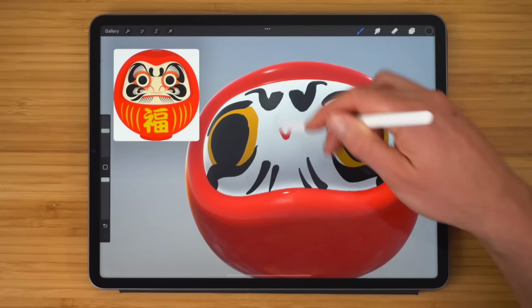So I can increase the amount here, and you can see that metallic property. I can control down the roughness, and you can see how I'm adding or removing roughness on that metal. And another cool thing is, in the metallic source or roughness source, we can actually add in grunge maps. So if I tap on this edit button, I can import a grunge material using this source library, and let's do grunge, because why not?